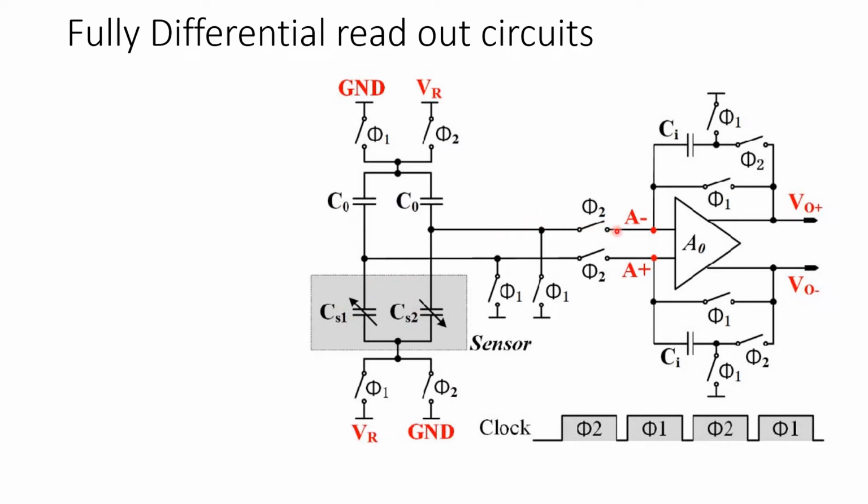If you look at the inputs, we will see typically one of the stages will be an active circuit phase, the other one would be a reset phase. Let us identify which is a reset phase among this. So reset phases, all the clock phases which ensure that the capacitance get discharged, can be called a reset phase. Now let us do a quick analysis.